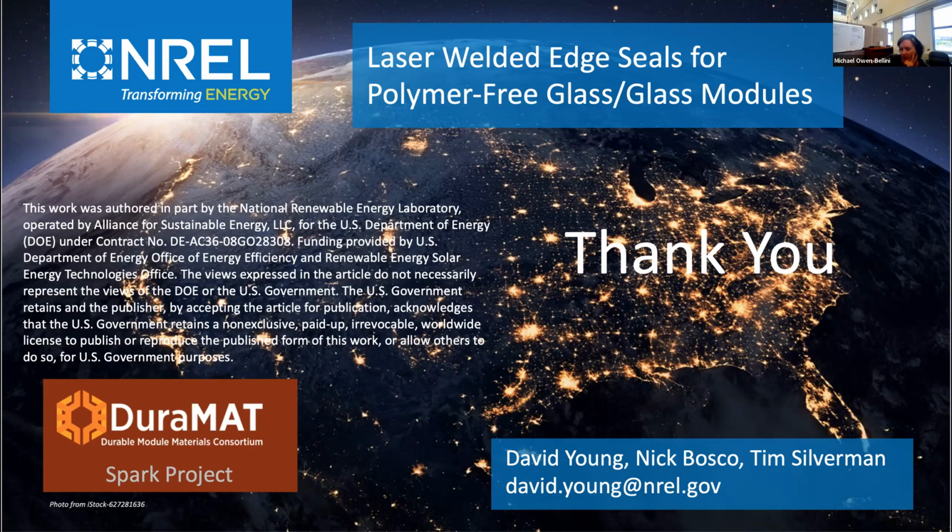Another question from Anonymous, which I think you may have answered in the talk, but I'm not sure. Was this study using tempered glass, or is there an issue with using tempered glass? Yeah, that's always a good question too. We did not use tempered glass. We actually bought tempered glass to try it, but it had a little bit of a dimpling on it, and the dimpling was enough that it diffused the laser, so we weren't able to get a weld.